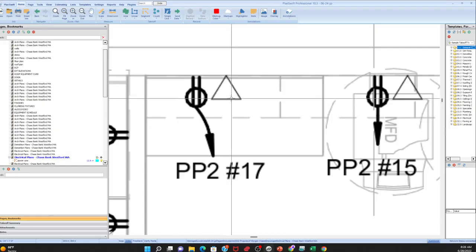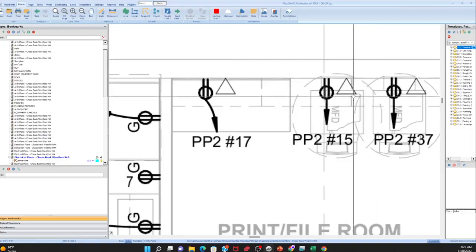So for the high voltage electrician, they would provide only what? The junction box and conduit to the ceiling. So when I do this takeoff for any of these, I just say J-box communication or J-box voice or J-box whatever. I know automatically that I have to have either a 3/4 inch or an inch conduit. And it's always just to the ceiling, unless it says run it to the communications room or something.